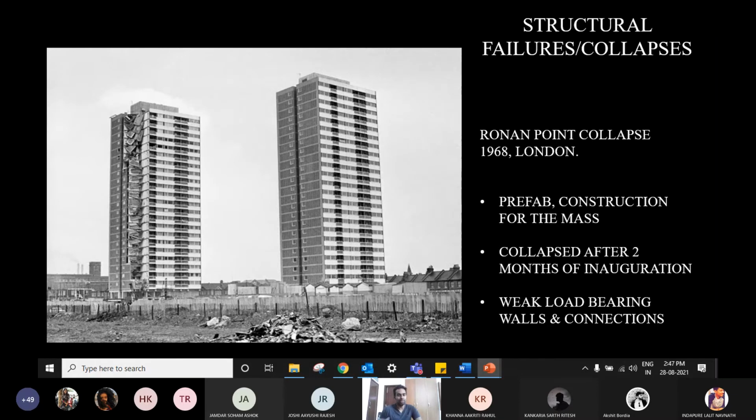It was an unfortunate explosion, and because of it, one of the walls, which is a load-bearing wall, was pushed away. This building doesn't have columns. All these components are prefabricated and assembled, and these walls are load-bearing. The wall fell off, pushed away, and there was nothing to take the weight of that portion of the building from the top 4 stories.